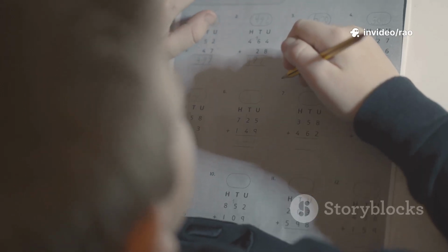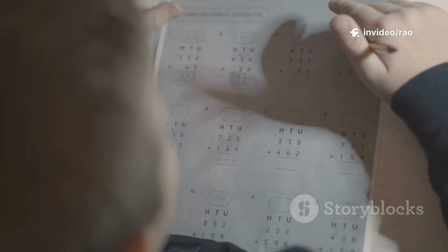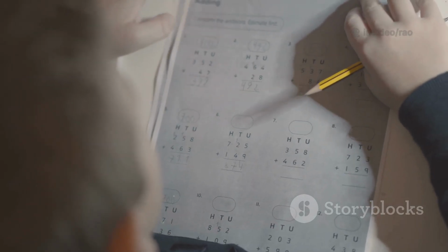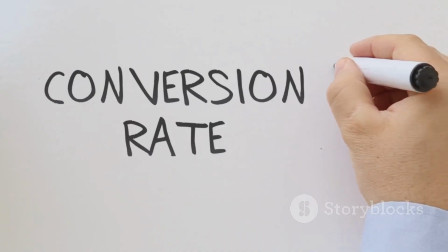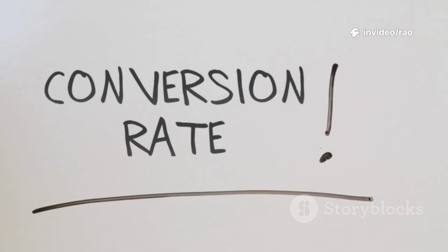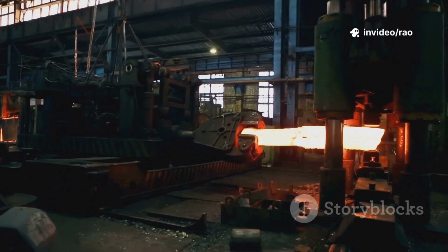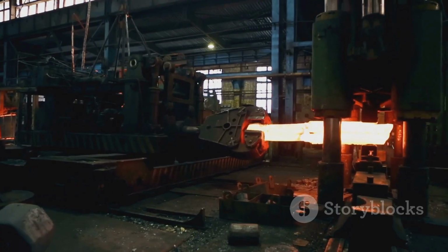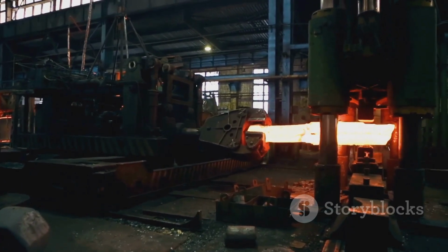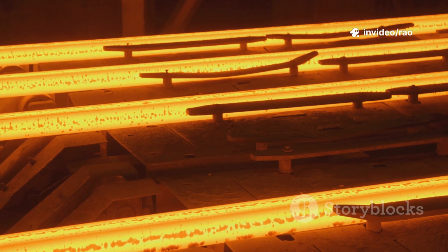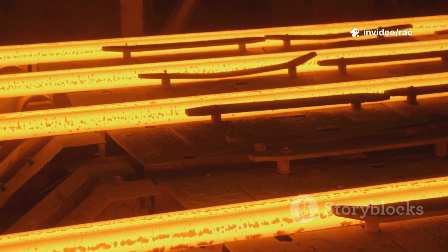Cutting length per main bar equals 4,000 mm plus 240 mm equals 4,240 mm. To make further calculations easier, especially for weight estimation, it is convenient to convert this length back to meters. Cutting length per main bar equals 4,240 millimeters divided by 1,000 equals 4.24 meters. Each of the 21 main bars will need to be cut to this exact length.